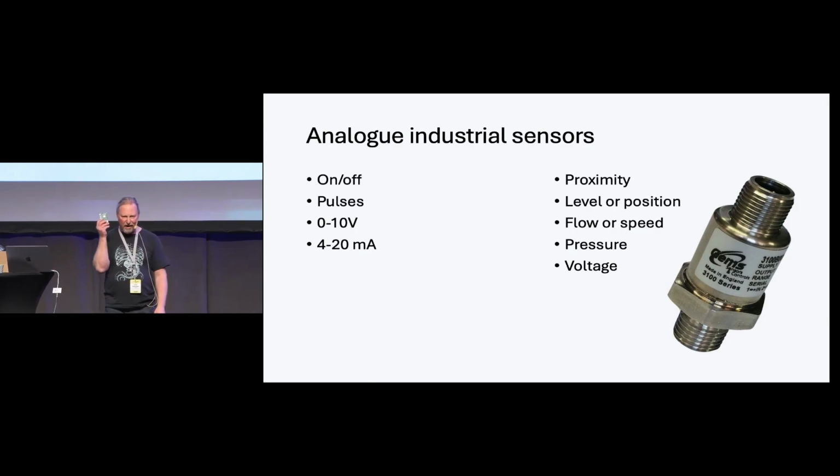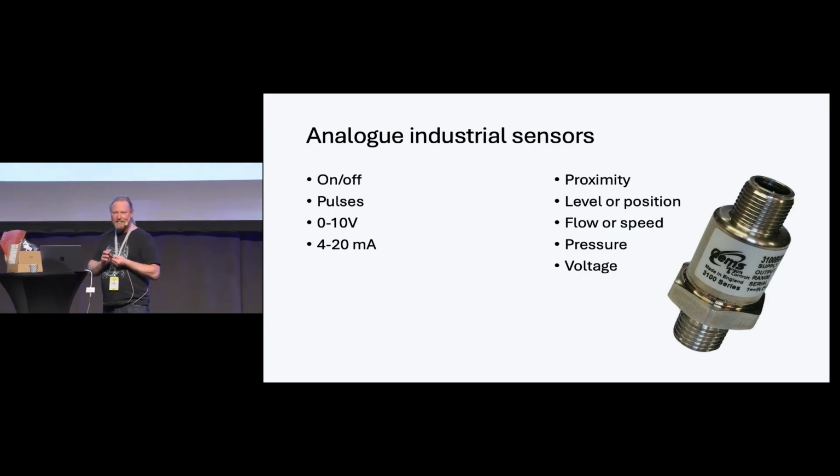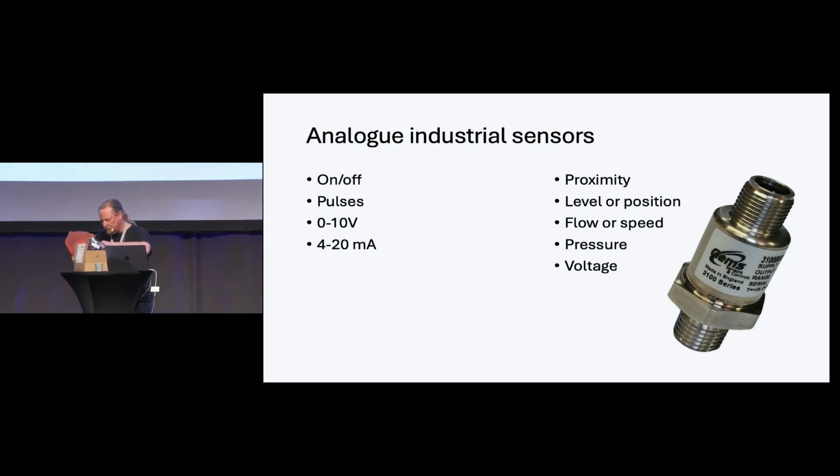but not for a Raspberry Pi. Not alone. First of all, don't connect 10-volt signals into this one. It will fry. And it doesn't accept analog signals. But the solution is easy. You get something like this.